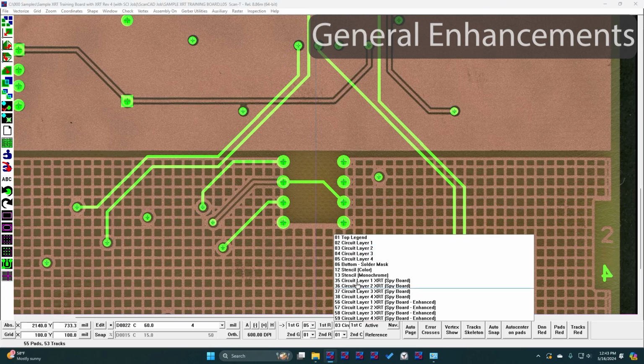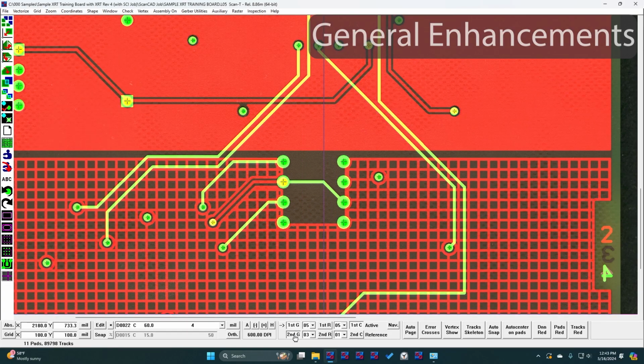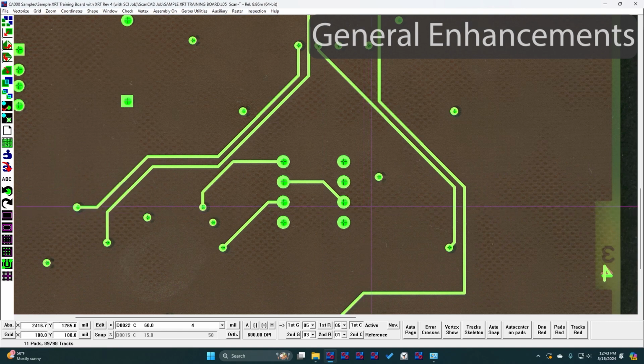You've got to go through and make sure to select the corresponding raster layer as well to make sure everything's synced up. And of course, same thing for the reference layers if I'd like to have a different reference layer displayed. So we hope you enjoyed that new function. We found it's just a nice way to save time so you don't have to escape and go back in periodically when you're either working on or inspecting different layers in a multi-layer job.